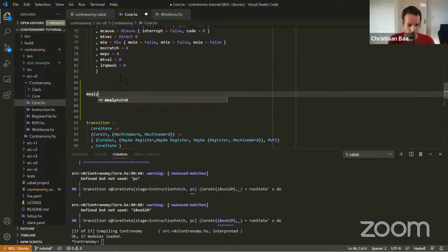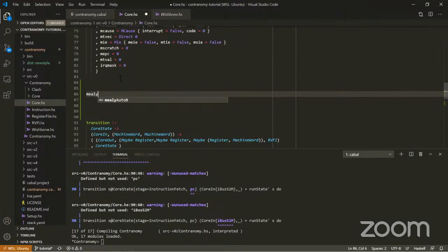In that case, what's the Wishbone story for this? Does it latch the address until the memory becomes ready to serve me, or does the CPU have to do that? Does it include some kind of address in the result to tell the CPU that this is the read result for this particular read request?